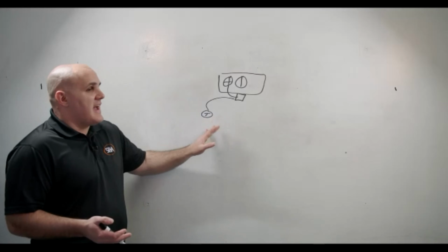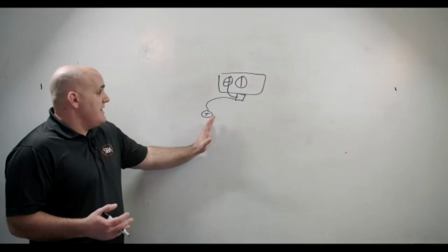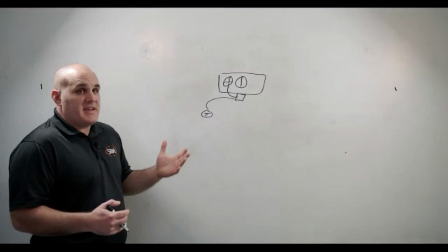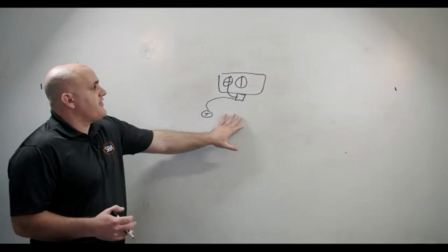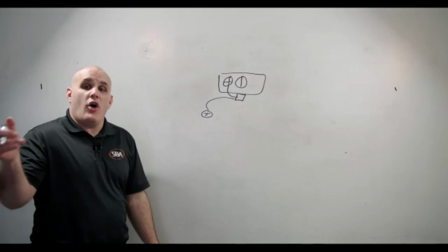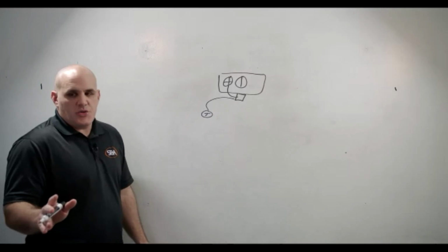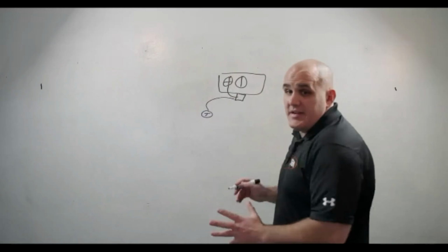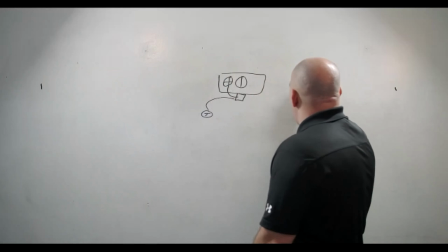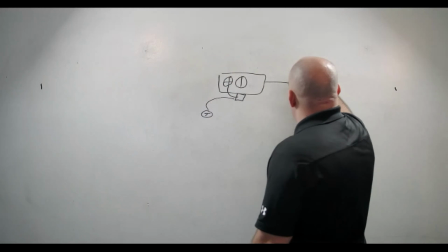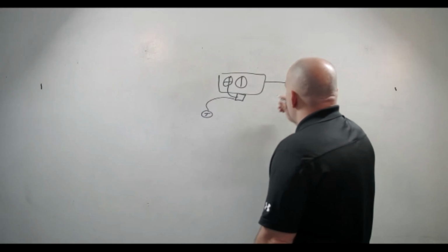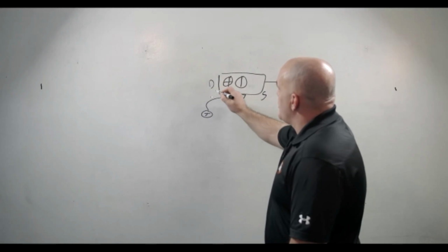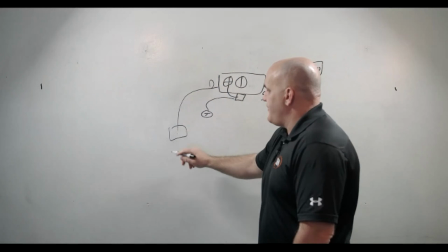Then once we've verified that our physical inputs are accurate, we have verified that it is actually indeed hot, we have to say, how do we cool it down? Well, we cool it down by getting the appropriate cooling airflow. So the first thing I like to check, once again, is it all spaces or just one space? In this situation, we're going to say it's just one space. How does air come into a terminal unit, right? It comes from the main AHU into the terminal unit. So this is going to be our supply side, and this is going to be our discharge side, and our discharge side is going to go down to a diffuser, right?